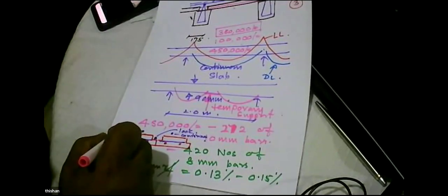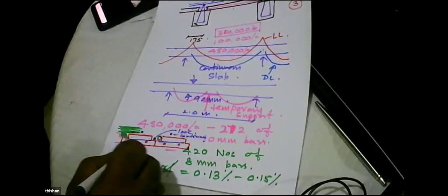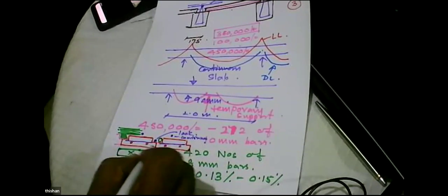So this, and then when you are concreting, here you get another one. When you are concreting, what happens? The concrete will fill up all this area. Then if you want to have a conduit, you can run the conduit there without having any durability issues. So there is a particular advantage of not using this shape, but using this shape. So this is not good, this is good.